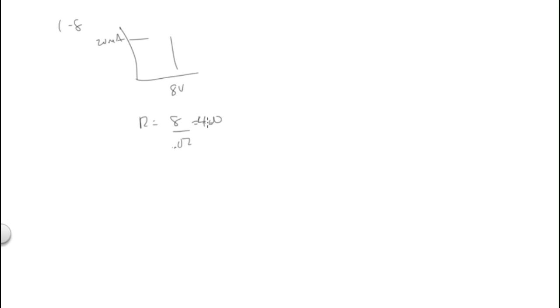Okay. Now they want to know what V is. V equals 0.035, 35 milliamps times 400. So 400 times 0.035 is 14 volts. What is the resistance? Right there's the resistance. Okay, moving along. Some more.